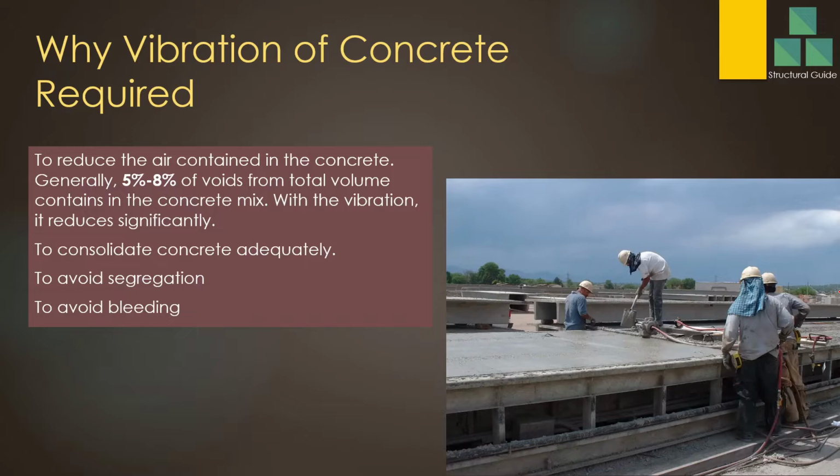Why is vibration of concrete important? It reduces the voids in the concrete, or it reduces the air entrapped in the concrete. Generally, 5 to 8% air is entrapped in the concrete due to the mixing process. So we need to remove that air, we need to reduce that air content. We also use vibration to consolidate the concrete adequately. To avoid segregation, we do the vibration. To avoid bleeding, we do the vibration.